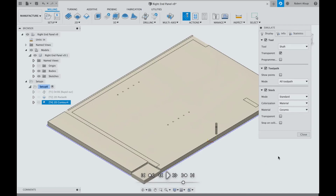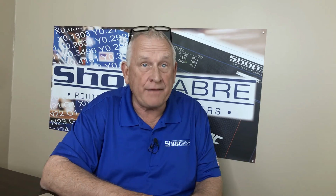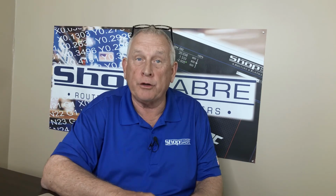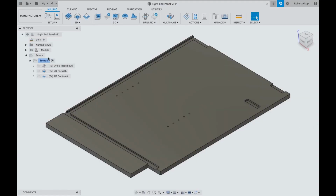We'll close that. Now that we've created the toolpaths we need, there is a way to save those as templates in Fusion 360 and then apply them to other parts. Let's take a look at how that's done. Okay, let's do a little housekeeping. Let's rename this. Let's call this right end. Okay, that's a drill. Let's call this a 5mm drill. Let's call this a dado.